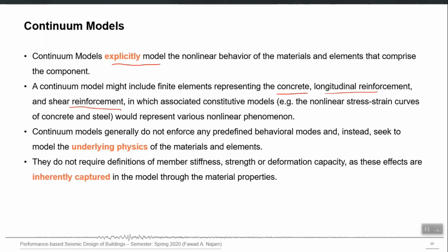But obviously this is a very detailed model, and it is trying to simulate the underlying physics of the material and element. So no predefined behavioral modes are enforced. Like we do not tell the model that the relationship between a particular action and deformation, like moment and curvature, moment and rotation, should be this one. We do not enforce any behavior, any action versus deformation. We define material, and whatever is the nonlinear action, it automatically manifests from that material behavior, right?